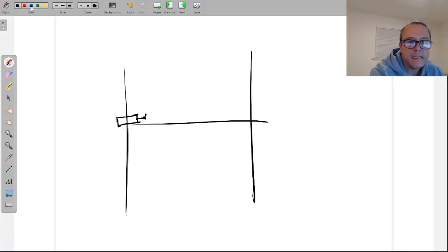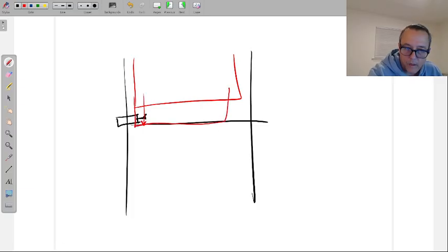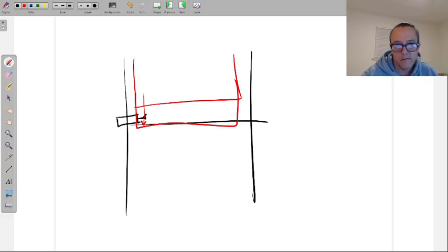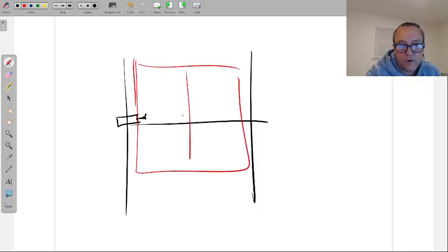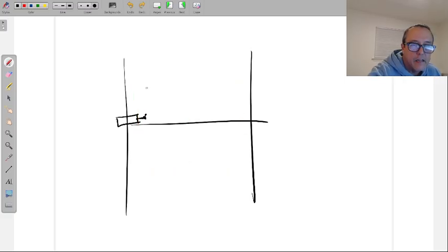As the elevator was coming down, it would trigger the limit switch. And once that limit switch closes or opens, whatever, I think it was closed, now the doors are going to open on the elevator. So if you ever got stuck in an elevator because it went past the floor, and then they opened the doors and you realized you were half of the floor is there, or a little bit too high or a little bit too low, very likely the limit switch was bypassed, or it wasn't actuated correctly.